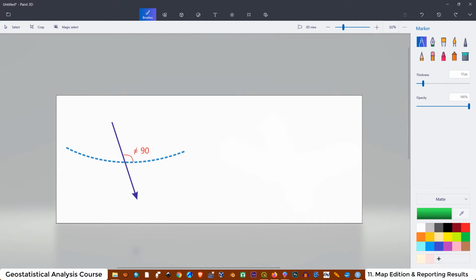Unfortunately, I have to say that I saw a lot of groundwater flow maps where the groundwater flow direction line is not perpendicular to the contour line, and the reason is not because they calculated the anisotropy of the hydraulic conductivity and placed the arrow for the groundwater flow direction line according to the flow direction. The reason is because some people don't understand the relation between the groundwater contour and the groundwater flow direction line. And that's a very big issue, because if you are dealing with